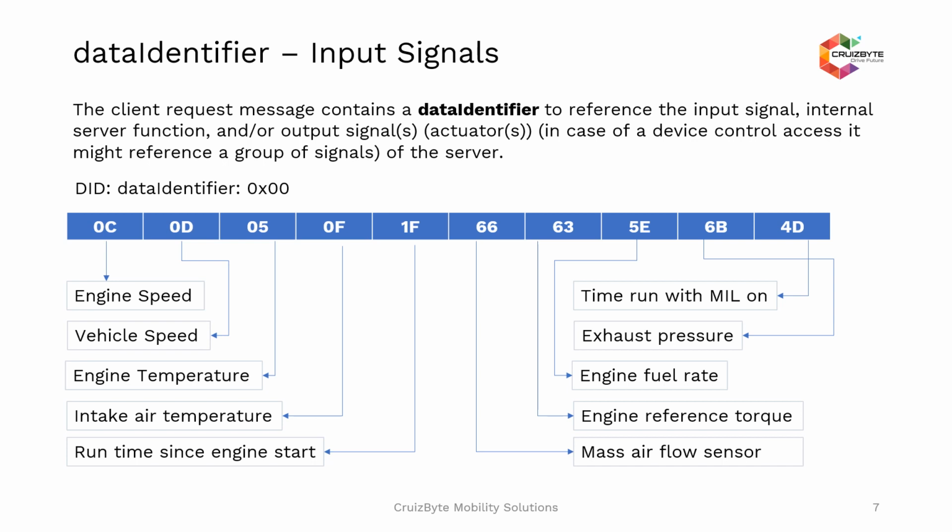Why are these data identifiers required? Since the ECU has several inputs, and there are several calculated values which are created internally by the software, when the vehicle goes for a service, if there is some issue with a specific circuit or with specific components in the vehicle, then this data is read through a service called read data by identifier.